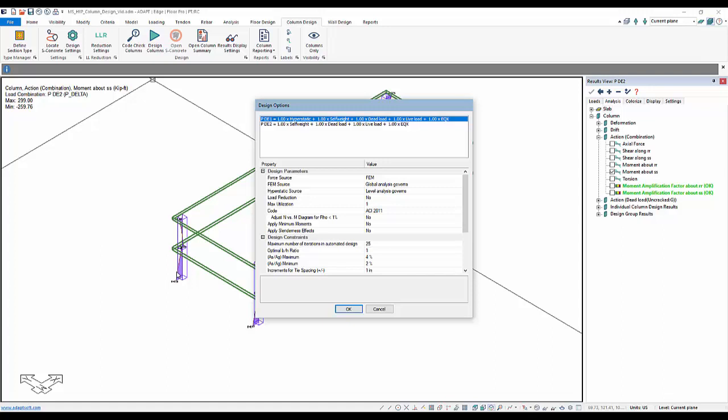When we go to stress cables and introduce those hyperstatic reactions, we can rerun the model in single level and source those particular reactions only for the hyperstatic case, which is also included, let's say, here in PDelta 1, and the program will compile those reactions for the design. We're going to show that process now.